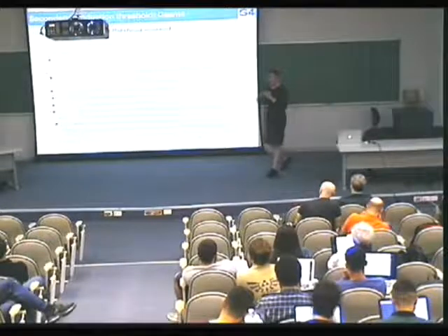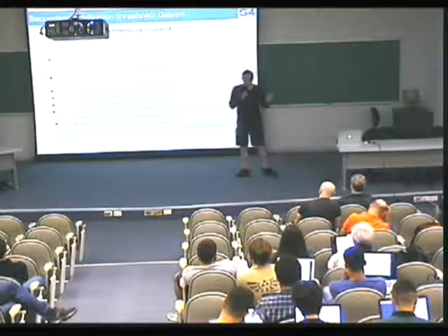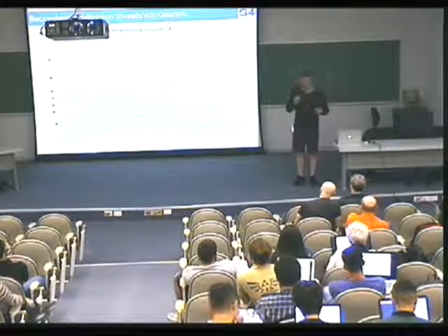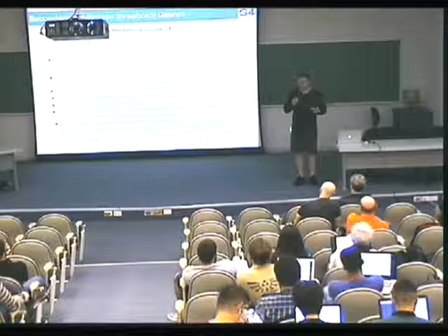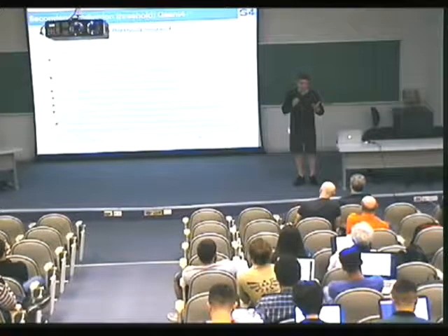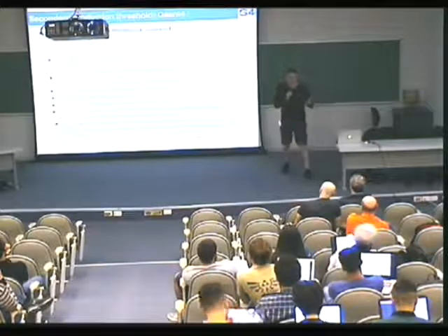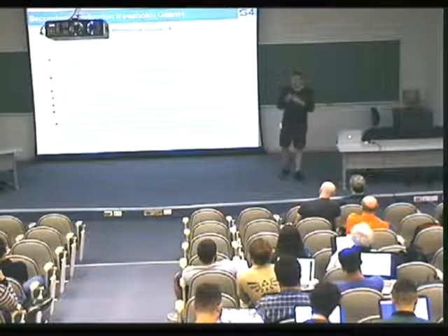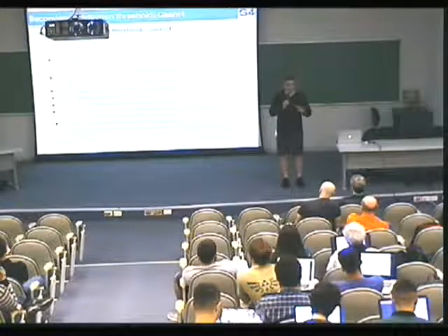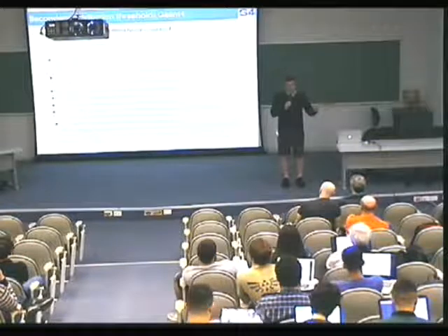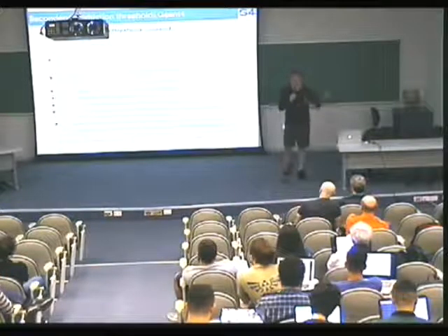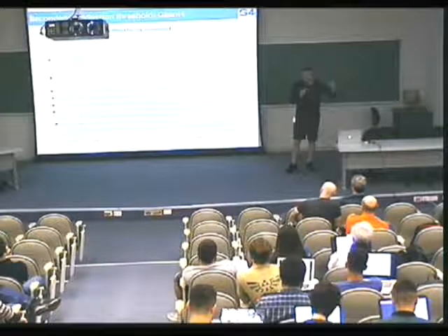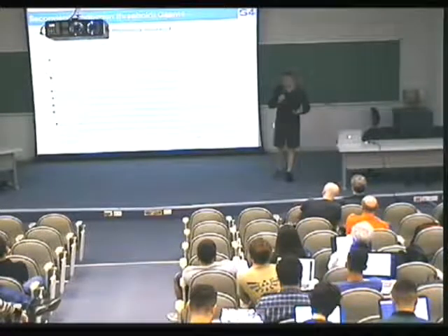Now, as I mentioned, this way of describing ionization and Bremsstrahlung is necessary. It's not necessary. Practically, you could set the secondary production threshold to 0 in case of Bremsstrahlung models, yes. In case of ionization, if you are using a proper model, proper theoretical description, that will be fine to produce even low energy secondary electrons. Then you can set it to 0.